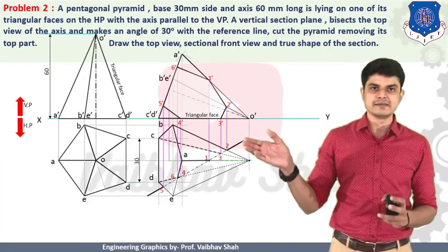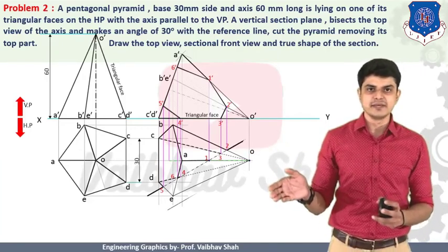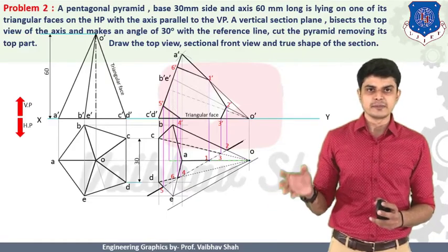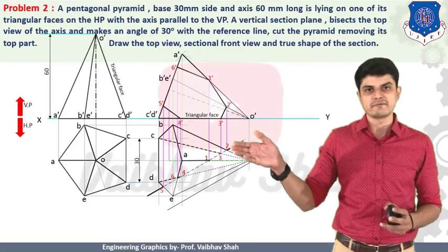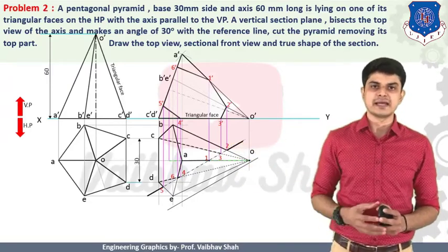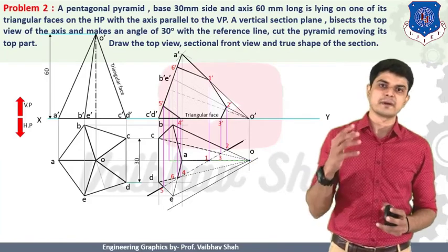So let us draw one line parallel to this line, and this will be your new line. So in place of drawing the perpendicular lines from your cutting plane, we are drawing one line parallel to your cutting plane line, and from that line we will generate perpendicular lines.